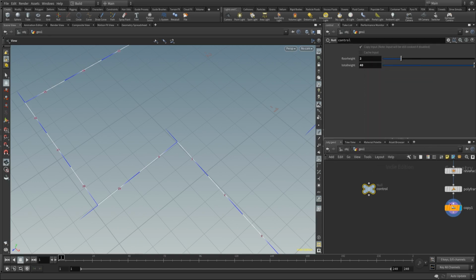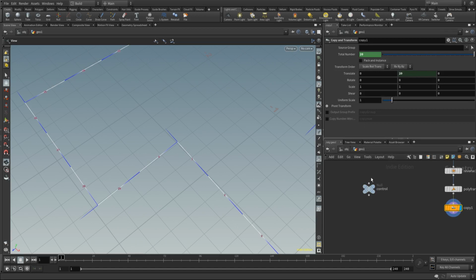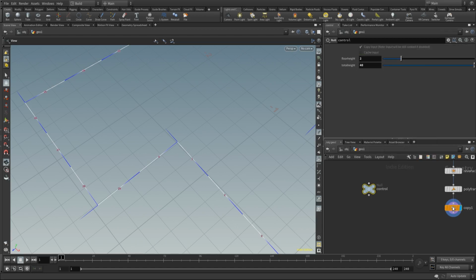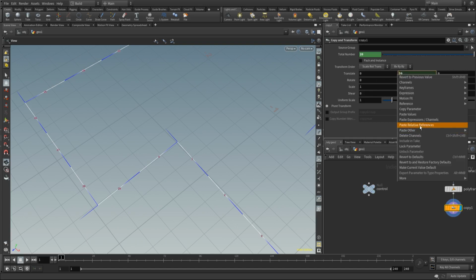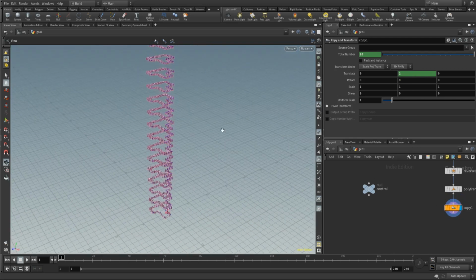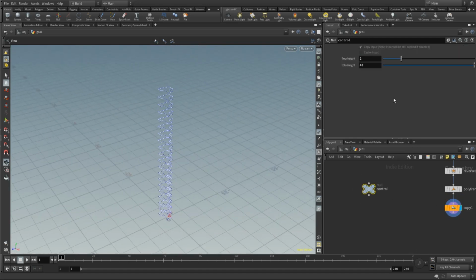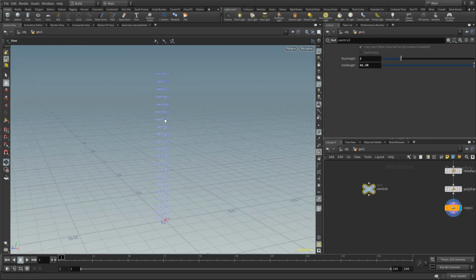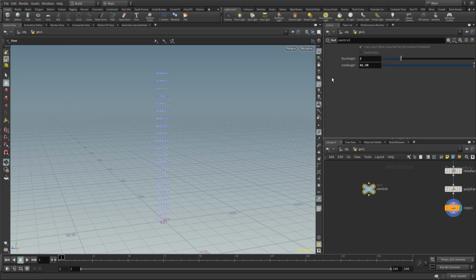Well, you could do 2 things. So right now we have the total amount of copies, and it's easier to take the total height and then again take the total height and divide it by this number. Okay, here we go. So right now I'm only using whole integers and everything divides into whole integers. But the cool thing about this is that if you right now would extend this value, the total height, everything goes smoothly. So you have a lot of control about the exact height. Maybe you want to have more control about the exact floor height, then you should set this up a little bit differently. But for now, we don't care that much about it.